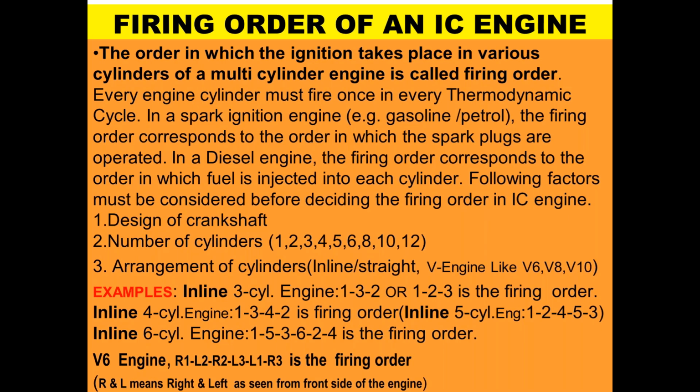Firing order of an IC engine. The order in which the ignition takes place in various cylinders of a multi-cylinder engine is called the firing order. Every engine cylinder must fire once in every thermodynamic cycle. In a spark ignition engine, that is gasoline or petrol, the firing order corresponds to the order in which the spark plugs are operated. In a diesel engine, the firing order corresponds to the order in which fuel is injected into each cylinder.